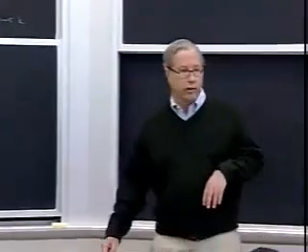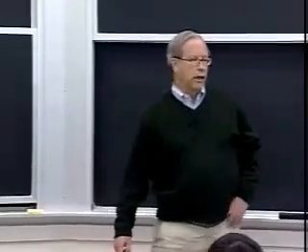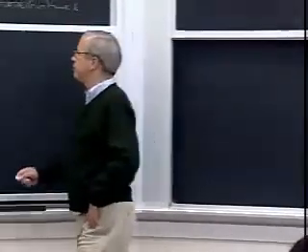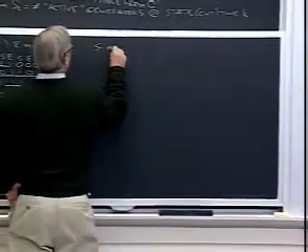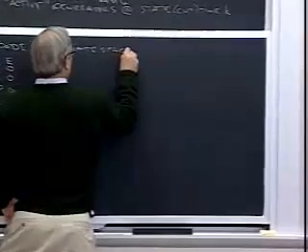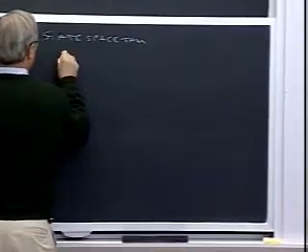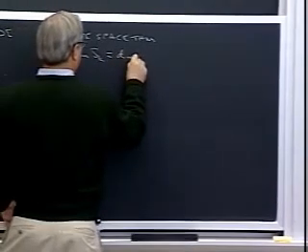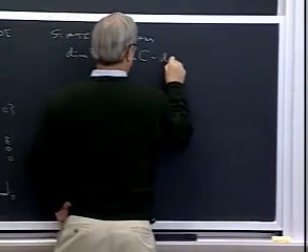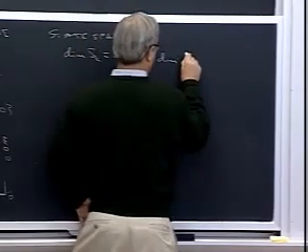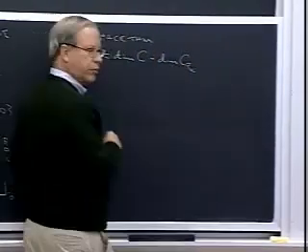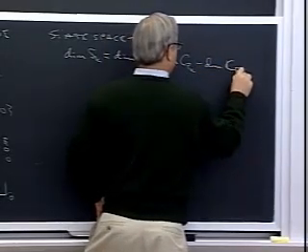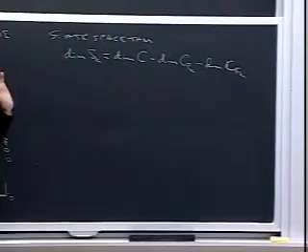Okay, question? We proved it in several steps. First, we had the state space theorem, which I gave to you in the following form. The dimension of the state space at time k is equal to the dimension of the code minus the dimension of the past subcode minus the dimension of the future subcode at time k, relative to this cut time.